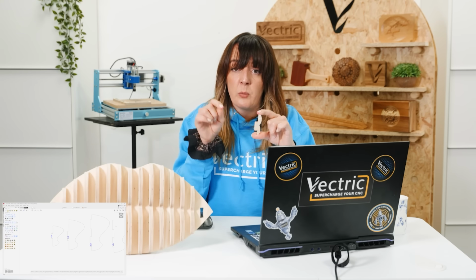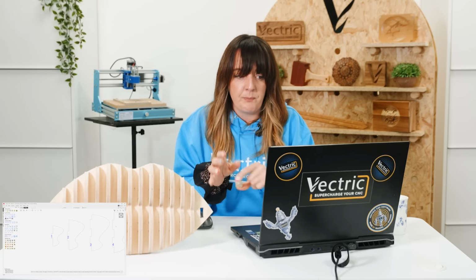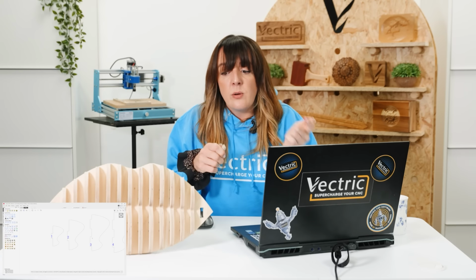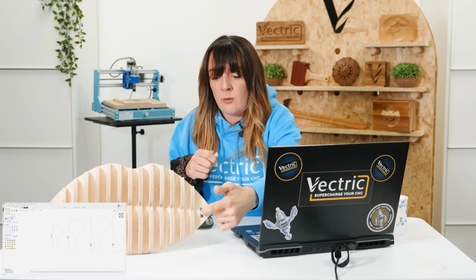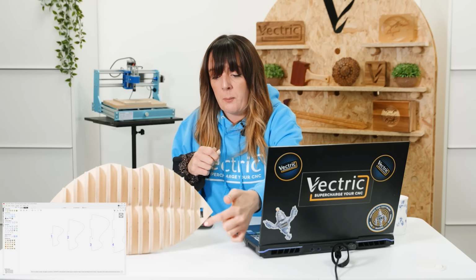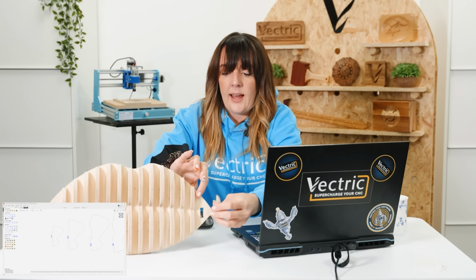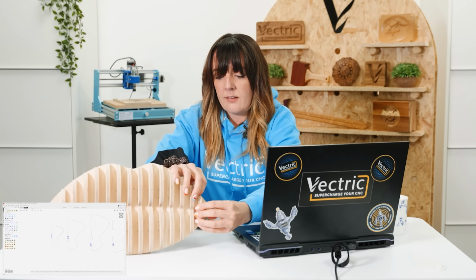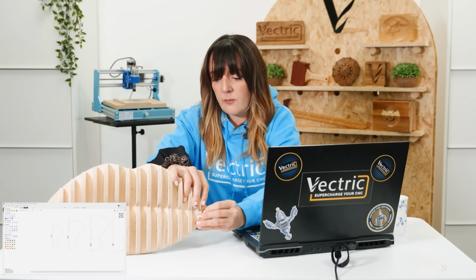And this will ensure that we cut through those corners so that we can actually slot it in. The idea here is we're going to be slotting into every internal corner of all of these profile parts, and also the backboard as well. So every slot that we've got on the backboard, we need to ensure that all four corners have a fillet in it, okay? So we're going to look at using the fillet tool there.